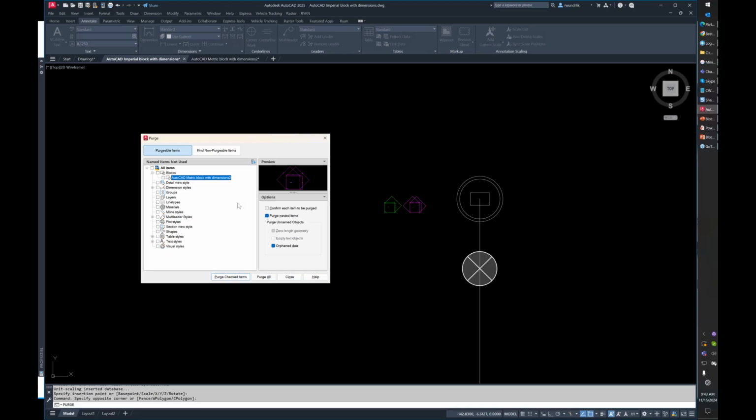So you might want to try creating an attribute and putting a field in the attribute, and then when you insert it, don't just hit OK at the attribute definition when it's asking you to edit. Then it should inherit the correct properties. Unless you're pointing to something in the block itself, then it may or may not, depending on what you're trying to point to.